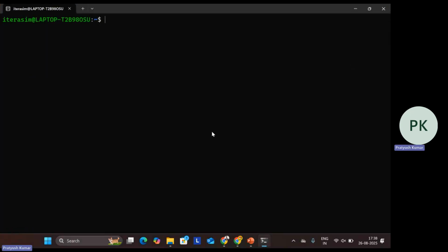So this is our terminal. Let's finish that example. First, we need to create the OpenFOAM 9 environment. Then we can type run, so that way we can go inside the run folder.